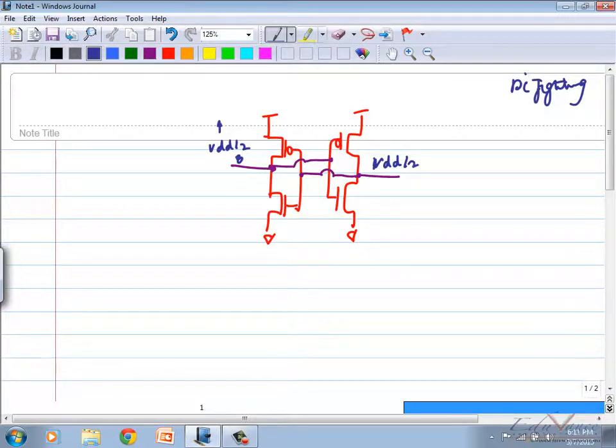But understand that the fundamental building block of any SRAM is a latch. It's a memory element. It has to hold and recirculate the data, once it has come in. Then you have your row enable or word lines, WL.